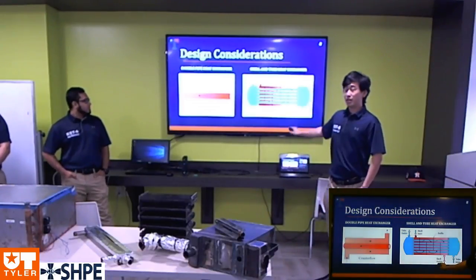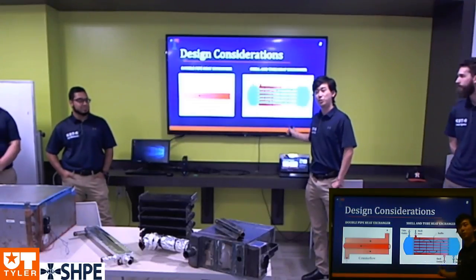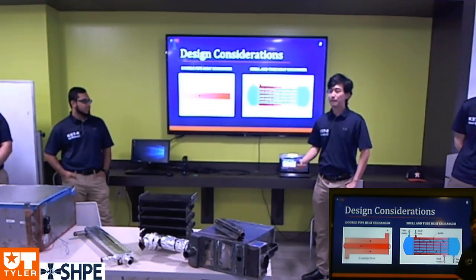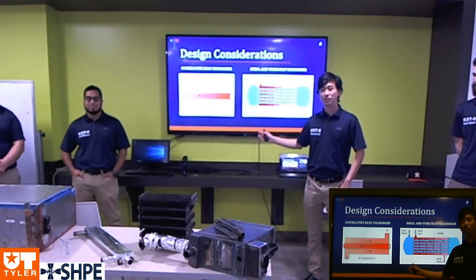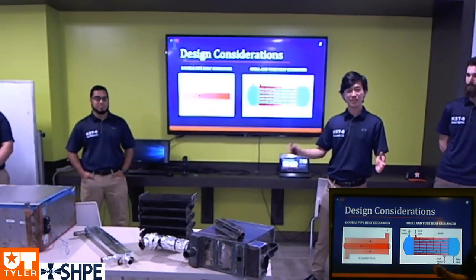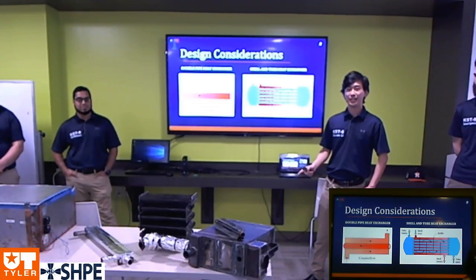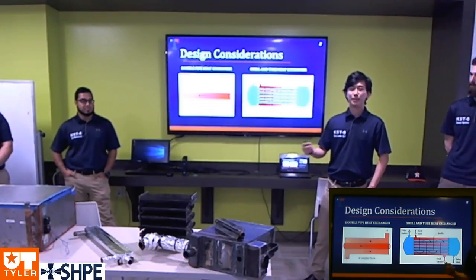After our research, we can see that the double pipe heat exchanger and the shell and tube heat exchanger came out on top. Each has their advantages, and each has one major disadvantage. For the double pipe heat exchanger, it had very excellent thermal transfer, but as it gets larger to hit the 800 degrees mark, the pressure drop becomes unacceptable. We're pushing more power through the fans than the power that is saved.